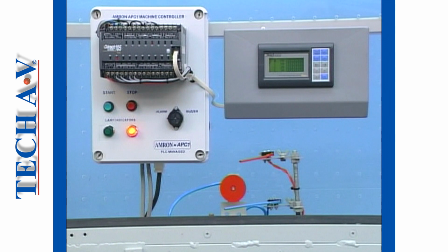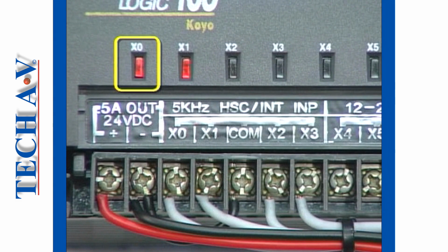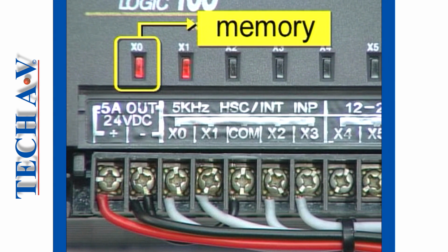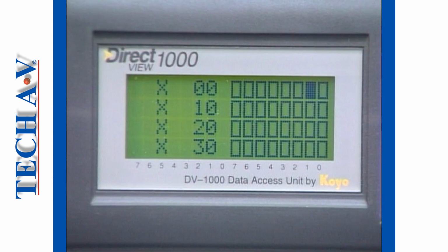Now it's time to start the conveyor, so we activate the start switch, sending an on voltage signal to input X0. On the very next scan cycle, the signal is transferred to an input register somewhere in the application memory. This process is called updating the inputs. The memory switch or bit representing X0 changes state from a logical 0 to a 1, and the processor takes the necessary action when it has read the contents of the input register.